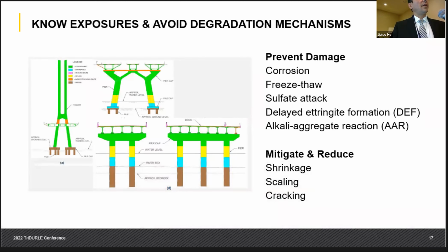Then about the degradation mechanisms, make sure the concrete is durable to all the degradation mechanisms you have. You're going to end up with corrosion exposure conditions, freezing and thawing, sulfate attack, right? You may end up with internal mechanisms like delayed ettringite formation and ASR, right? All of those, you need to make sure you manage them, right? Deemed to satisfy, what are the needs for that concrete to be durable.